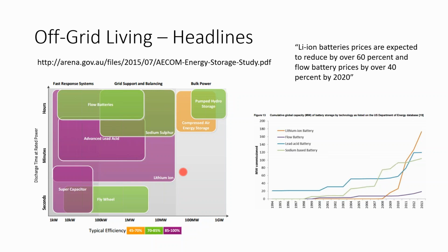If the bulk majority of your cost savings is coming from kilowatt demand reductions, remember, kilowatts are power. That's instantaneous. The kilowatt hour is energy. And so if most of your savings comes from kilowatts rather than kilowatt hours, the efficiency of the kilowatt hour component is not nearly as important as your capital expenditure to achieve those kilowatt savings. And for that matter, lithium ion costs so much more than flooded lead acid that the capacity becomes an issue.